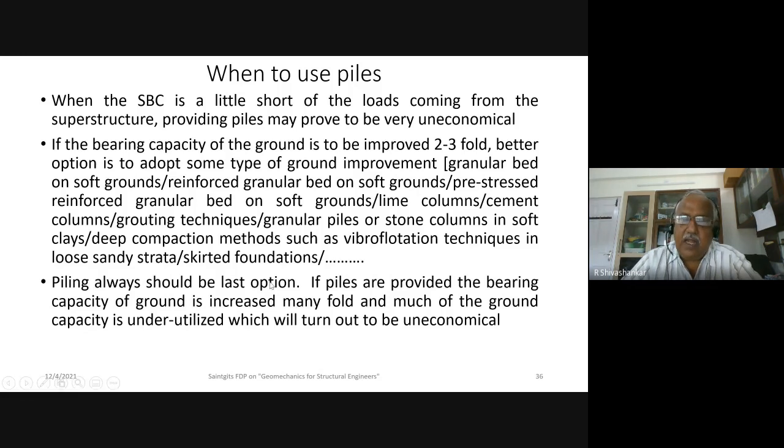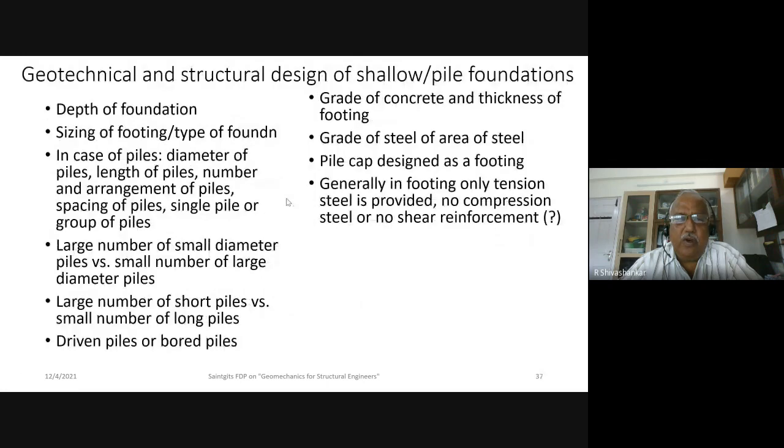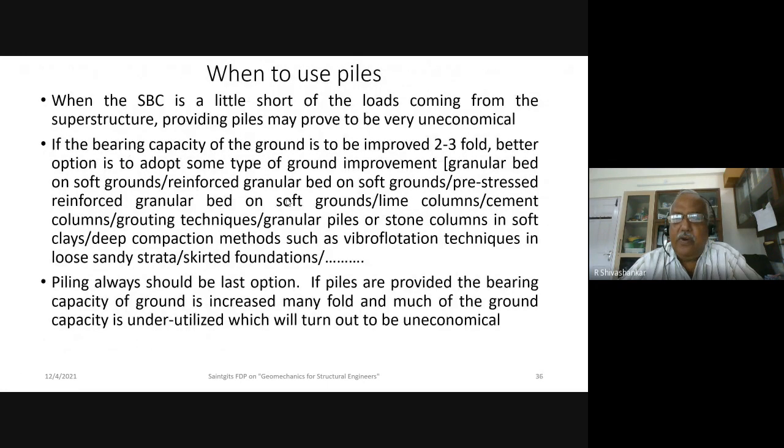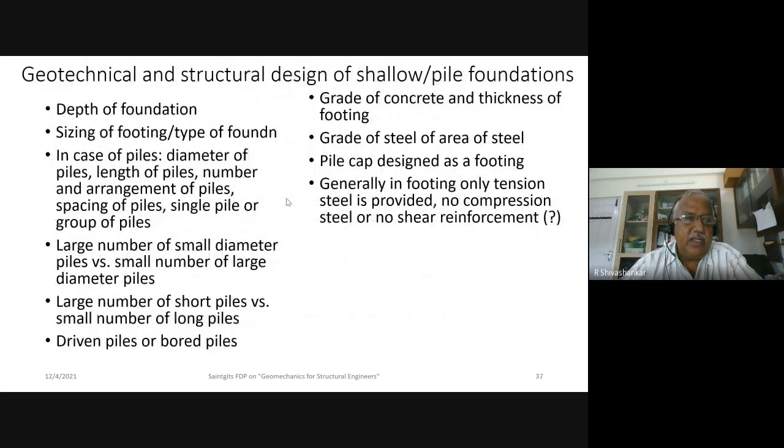I don't need that high bearing capacity. Maybe I just need to increase my bearing capacity 2 to 3 times. In such situations, there are many ground improvement techniques nowadays. So between the shallow foundation and the pile foundation, for just a little increase, we can go in for ground improvement techniques.